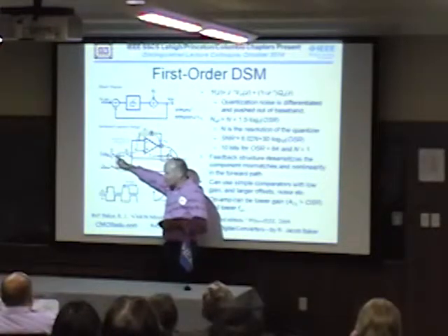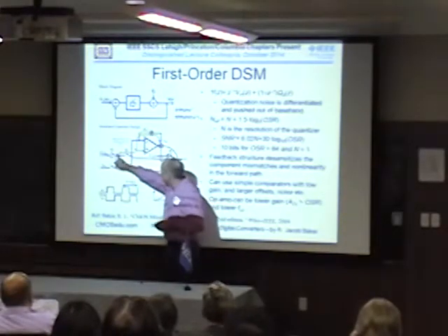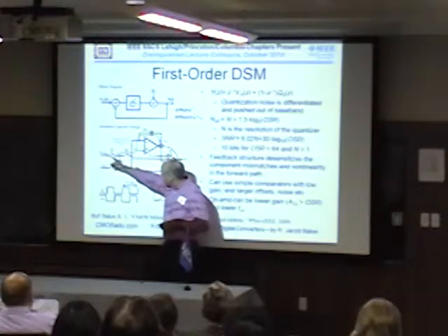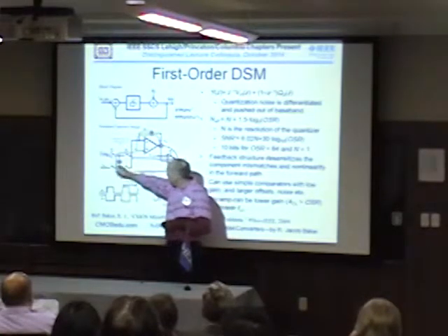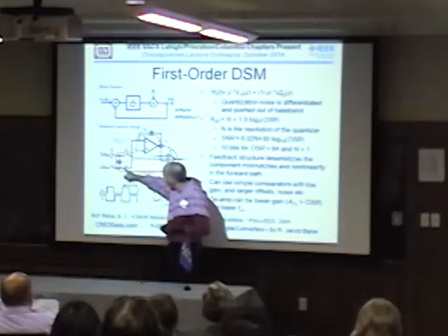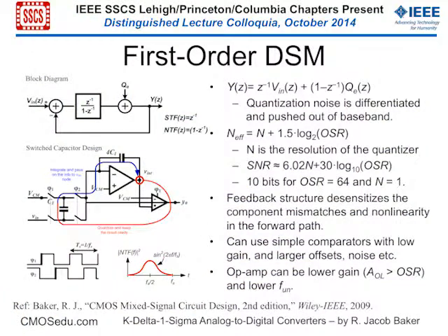Sample, I'll just use my finger the old-fashioned way. You sample the input signal onto the capacitor, VCM onto the other side. Then in the alternate cycle, you close the switch capacitor, or this switch here. And ideally, this side's at VCM, the same as the other side, the op-amp. And you dump the charge that's in excess or below VCM onto the feedback capacitor of the op-amp.